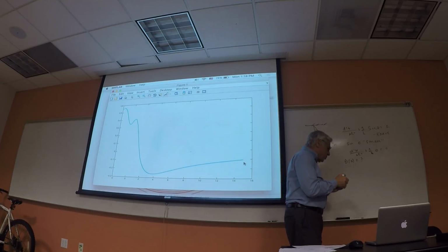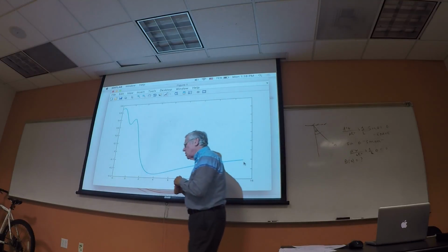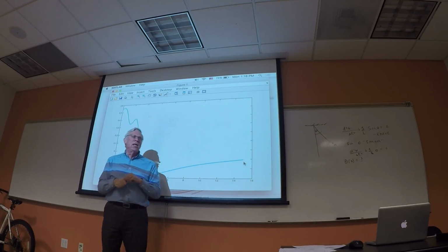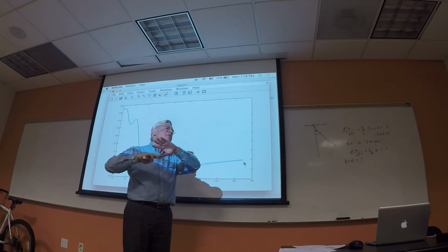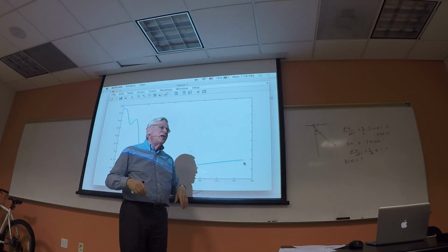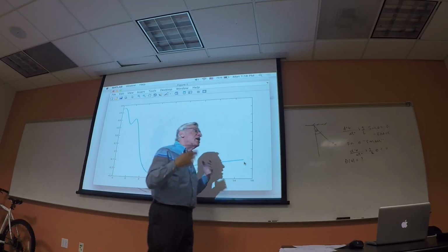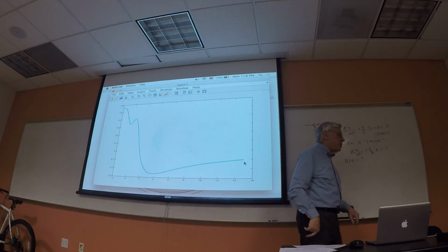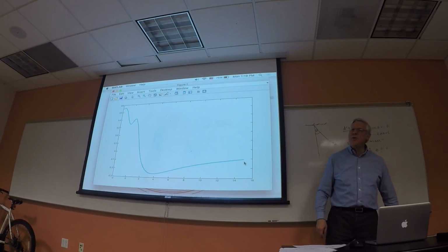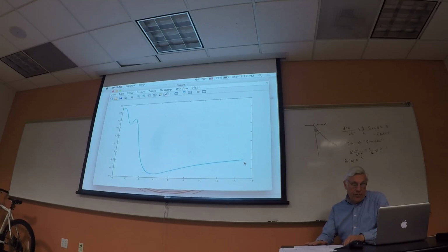So this is basically the answer. I'm doing a simple pendulum, but you can imagine in practice you would get some type of complicated system that you're modeling, and the real equations are nonlinear. And the control engineers always come to you. They love linear models, control guys. It's always because they're in love with Laplace transforms and transfer functions, and they always say, "Can you give me a linear model?" And in order to give something reliable, you have to say, can I linearize this or not? So this is an example, albeit very elementary, of how you would do that type of operation.